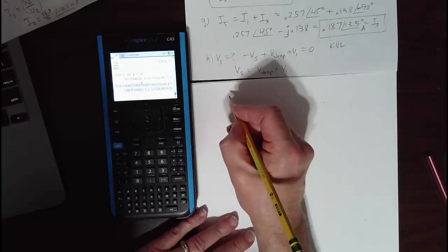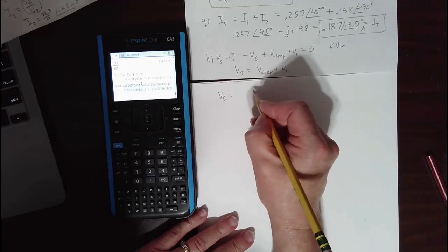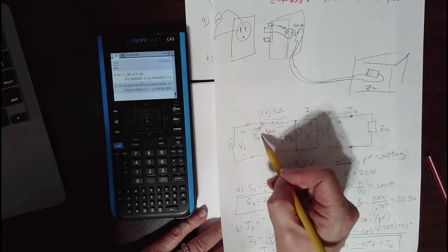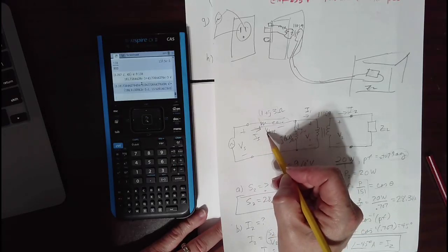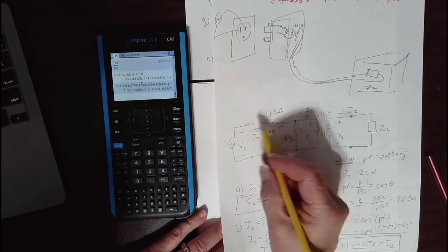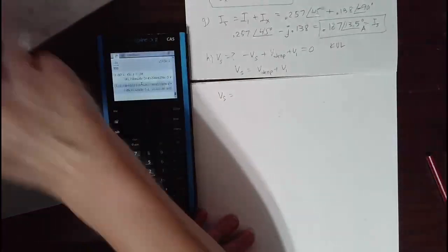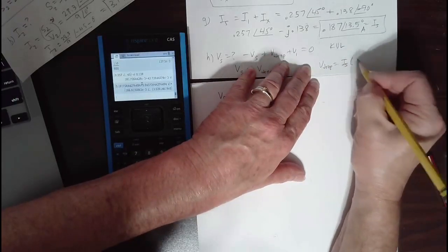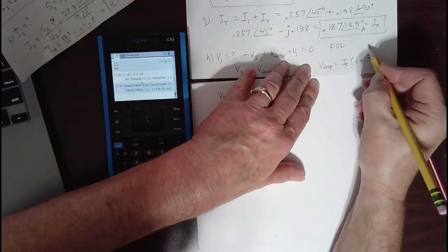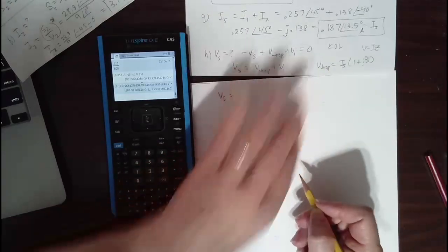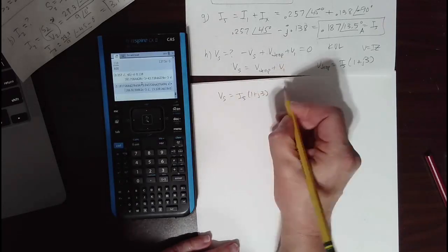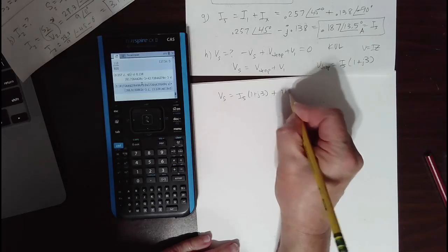Okay, so Vs then is, what is V drop? It's the voltage across this impedance, which is a combination of resistance and inductance. We can just use Ohm's law, V equals IZ, right? So V drop equals Is times this Z. V drop equals Is times 1 plus j3, Ohm's law. And so we put that in here, Is times 1 plus j3 plus V1, which was 110 angle 0.